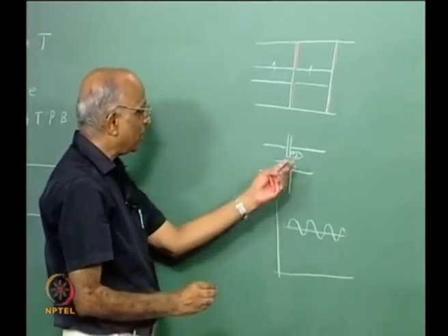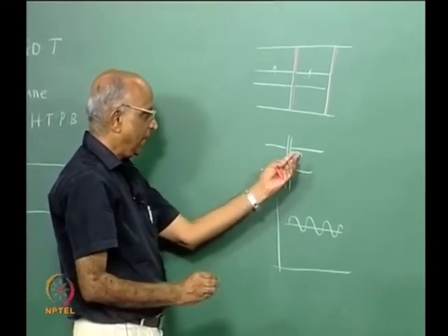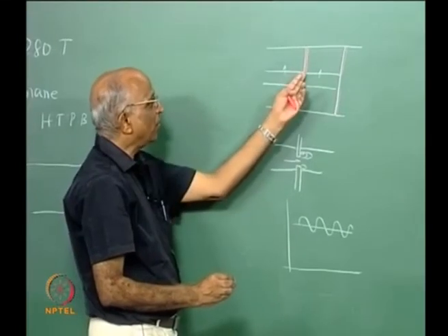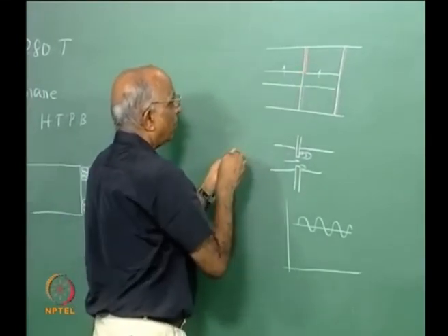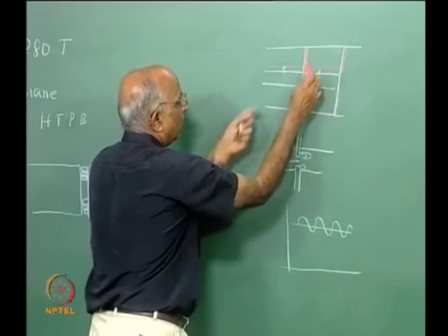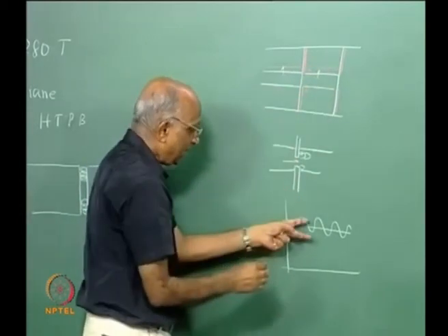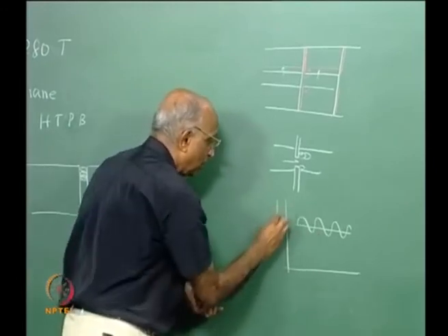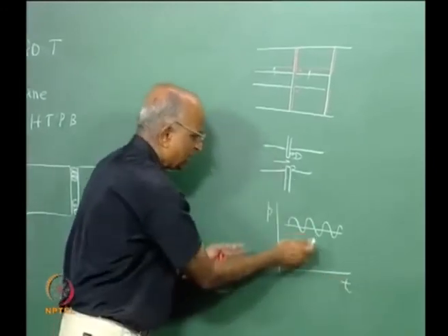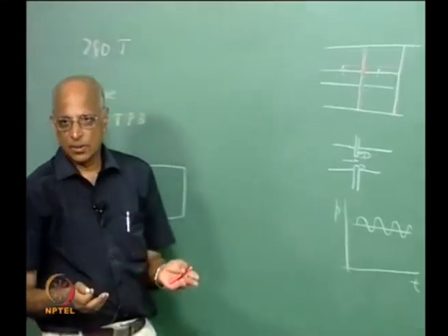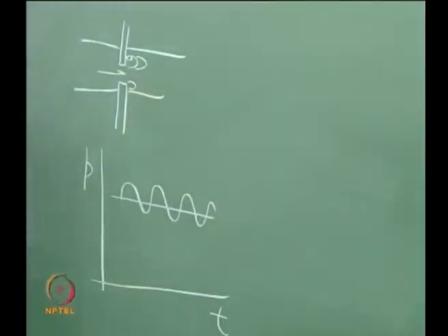The oscillation is because of the eddies formed, because this fellow projects when the propellant has burnt over here. I have this protrusion standing, and this causes the pressure to oscillate. We will see such mechanisms when we look at the chapter on combustion instability.